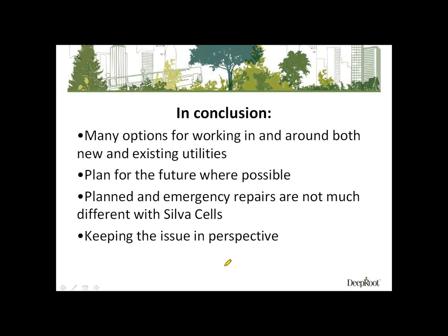But one thing about the Silva Cells too is the soil inside of them is not heavily compacted, and it's usually a free draining soil, and usually there's some type of drainage. Also, as it settles and the organic matter starts to break down a little bit, we're going to get a void underneath the decks.